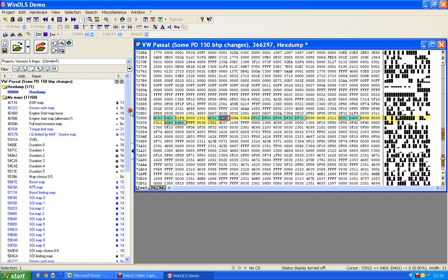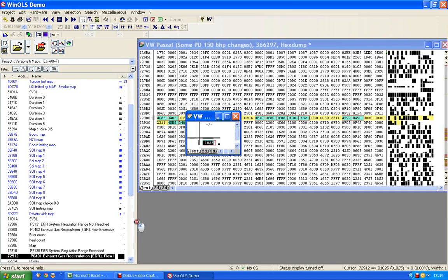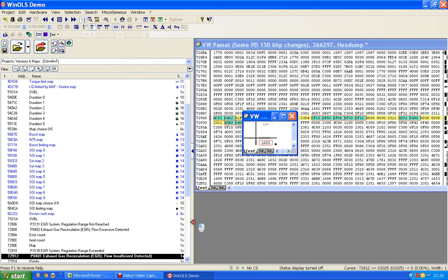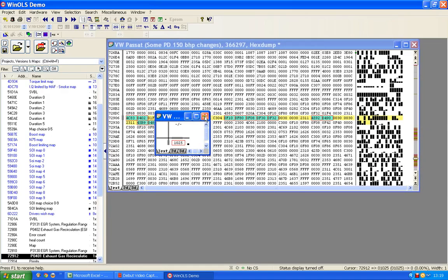I'll just get rid of that out of the way, because I've already had a little play with this to make life simpler for me when I'm explaining the video. So there we are, we've got a P401. If I click on that, it will open 1025. If I go down here, I get a message from myself because I've been here before. Exhaust gas recirculation, EGR, flow, and I can't see the rest, but if I do that, insufficient detected. So there we are, flow insufficient. Just going to close that down.